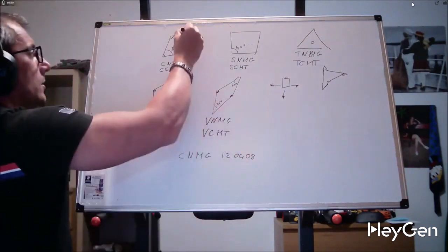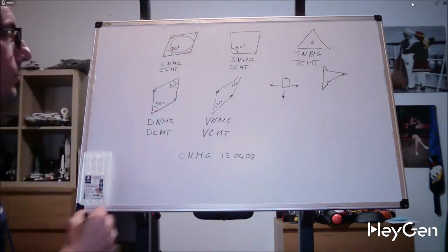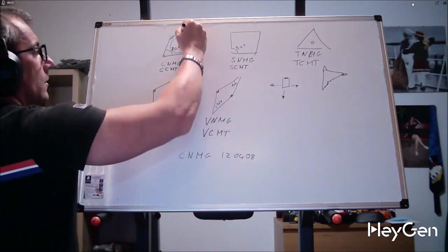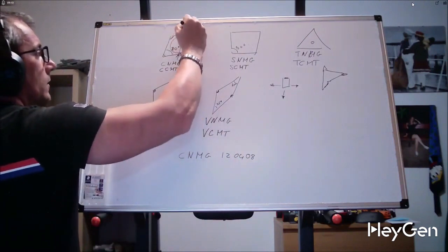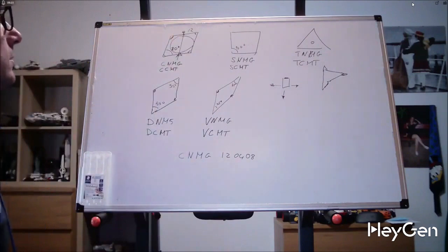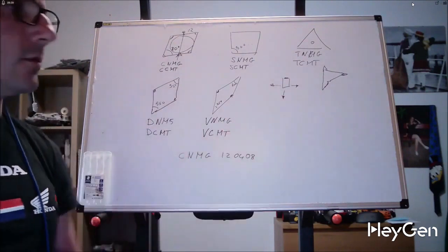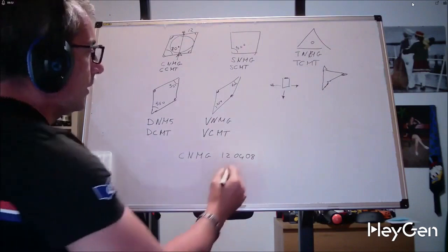12 is the diameter of the inscribable circle within the shape, so this distance will be 12 and defines the size of the inserts. There are inserts of 8, 12, 9 and 19. And for heavier machining, there are also larger inserts. So don't worry, those also exist.